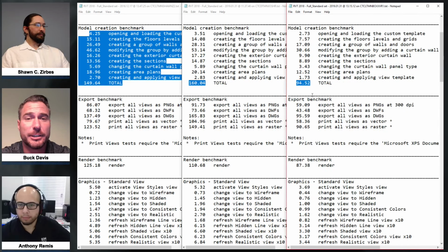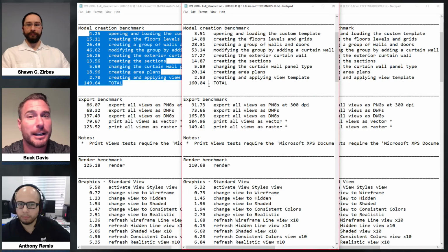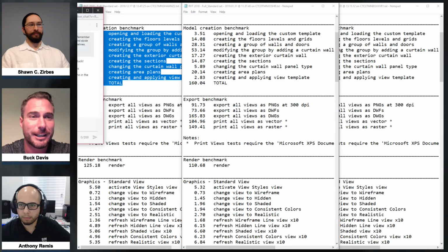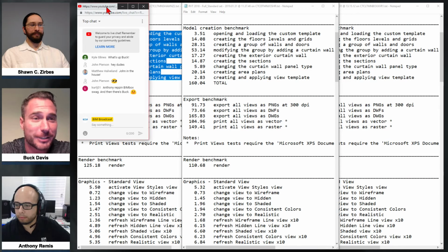Going back to the workstation you're showing in the middle, though, I just came from the MCAA technology event, and we had to have a discussion about what makes a workstation a BIM workstation. Because when I was at Balfour, they handed me a BIM workstation and a BIM workstation laptop, but that was a 4-core Xeon or a dual Xeon workstation that had an abysmal clock speed of like 1.2, and just because a manufacturer called it a BIM workstation, it wasn't the best thing for me.